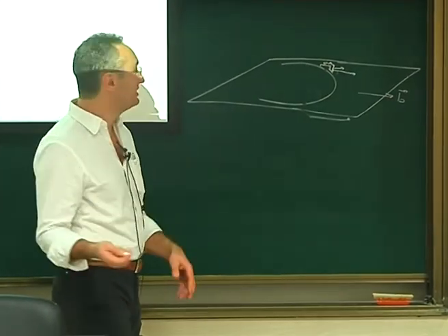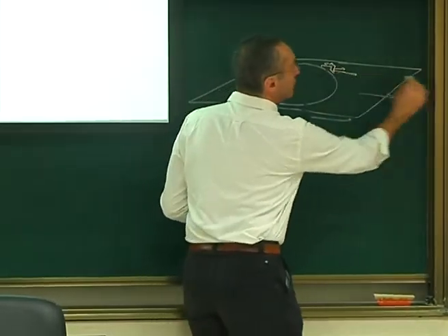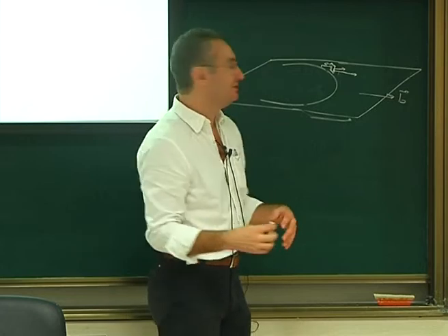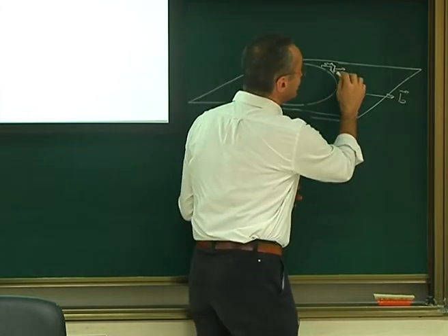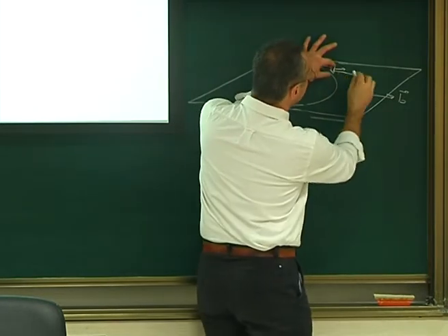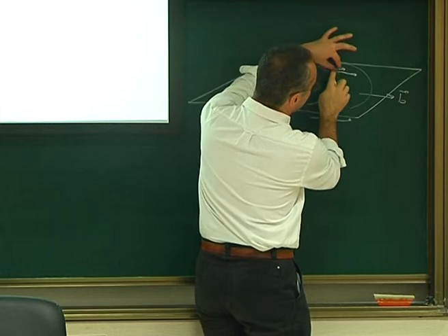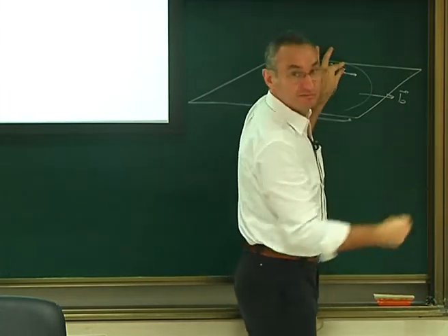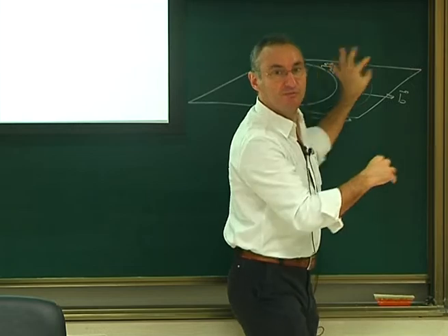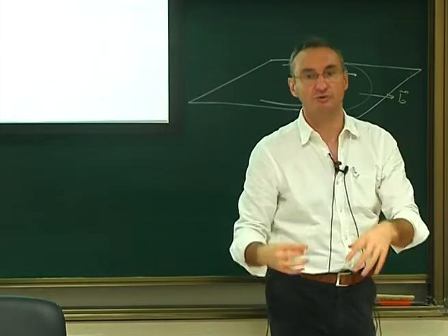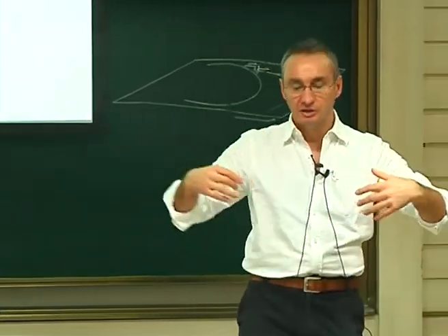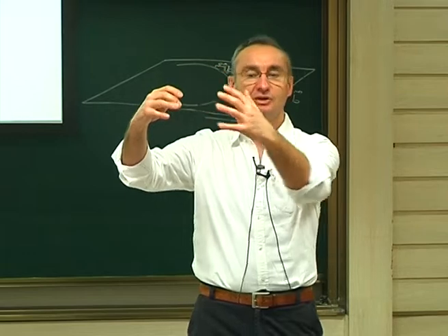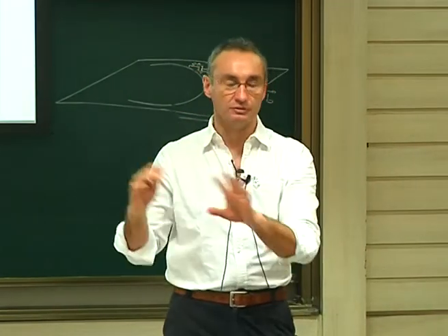But, as I said yesterday, it will not drag the dislocation up to the surface in one shot. It's not like that. Usually, it drags a bit and it detaches. So the loop will have been swept a bit, like this, at that place, and the dislocation escapes. So you need another one to move it further and further. So this takes time for the loops to reach the surface. It's not a single shot. You take your dislocation, you move to the surface, you cycle again, you take another shot. No. It's not like that.